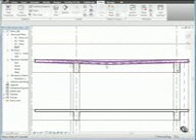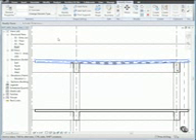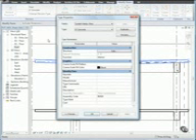Select the roof, and from the Element Properties drop-down, select Type Properties. In the Type Properties dialog, click Duplicate, and in the Name dialog, type Concrete Deck Tapered Insulation and click OK. Then, for the Structure Construction parameter, click Edit, and in the Edit Assembly dialog, select Layer 1 Core Boundary and click Insert.